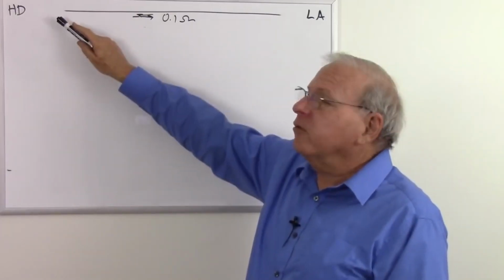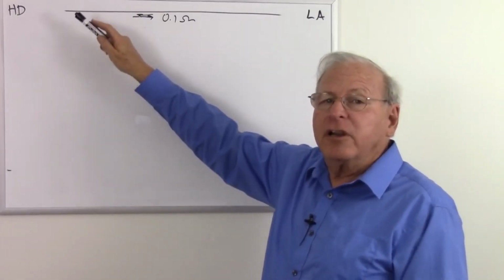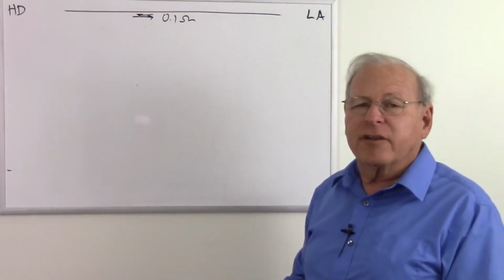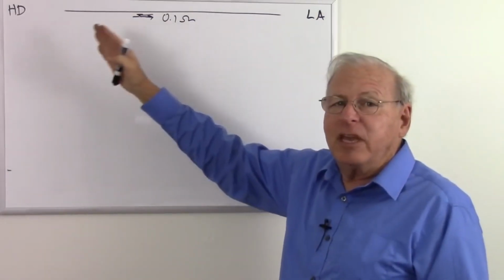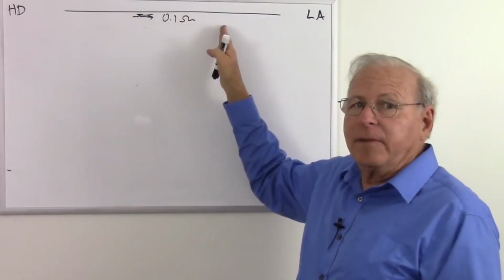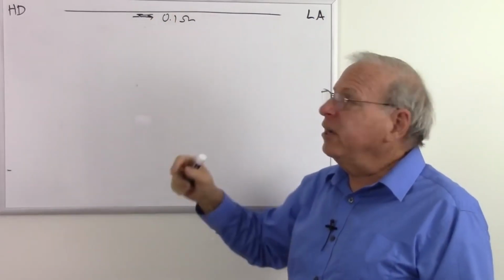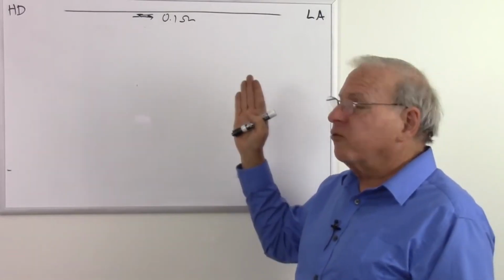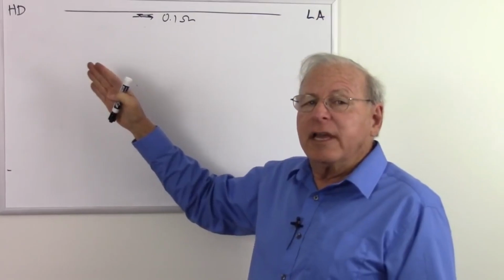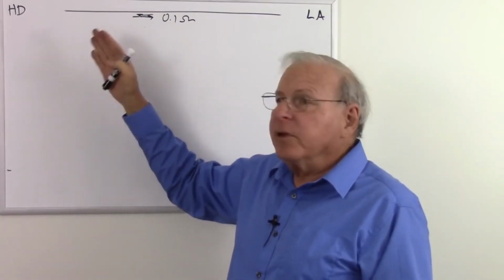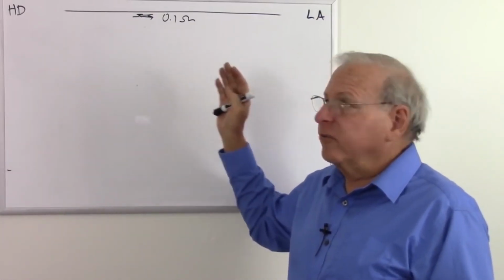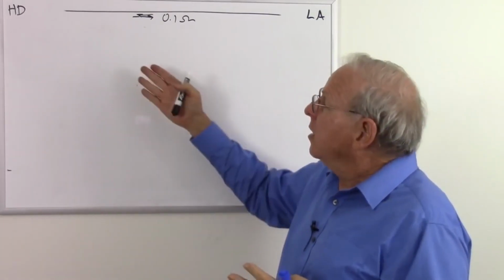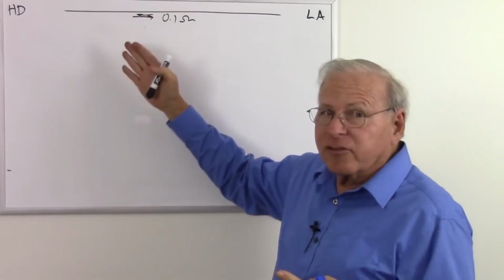Once we step this up to our 500 kilovolts, why don't we convert it to DC and send it over and then convert it back to AC at this end? Well, it's not cost effective. It's a lot cheaper to build the AC infrastructure than it is the DC, unless you go a certain distance. Somewhere around 500 kilometers, I believe, is where the trade-off point gets to where it's actually cheaper to build a DC system than an AC system. The wiring is cheaper, the towers are cheaper, and you'll see why in a moment, and their losses are less.